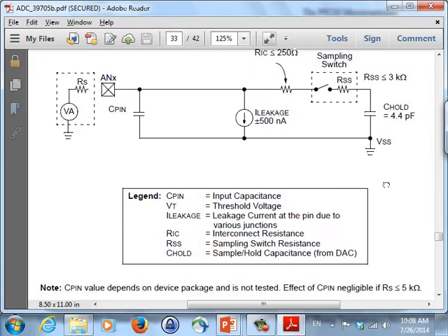All right, and the manual basically refers you to the electric characterization at the end, but doesn't give a whole lot of details. You need to know a little bit of analog to digital conversion to understand it. Now, PIC 18 gave a whole lot more details in its manual, and it gave detailed examples of how you calculate based on the temperature and so on, and they gave you the electric models that you would go from these resistance values and the temperatures to an RC value that gives you an exact time.